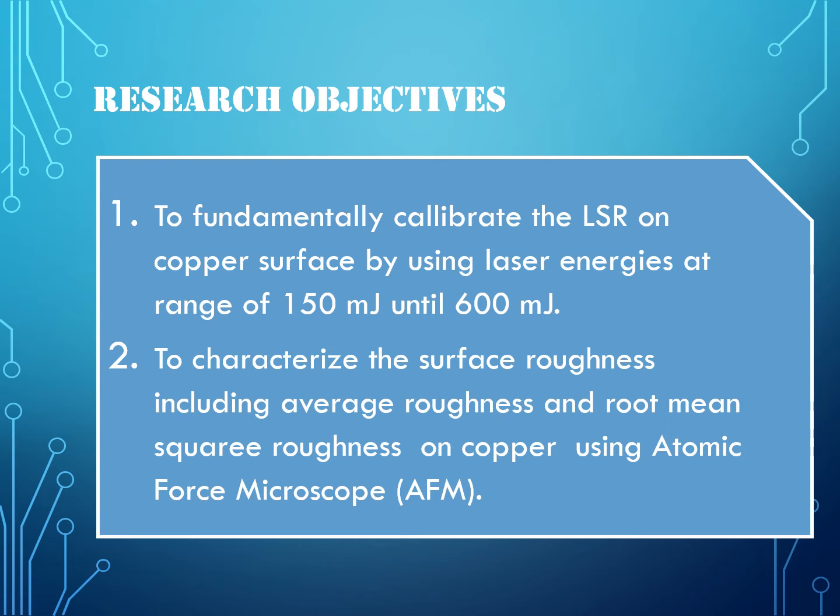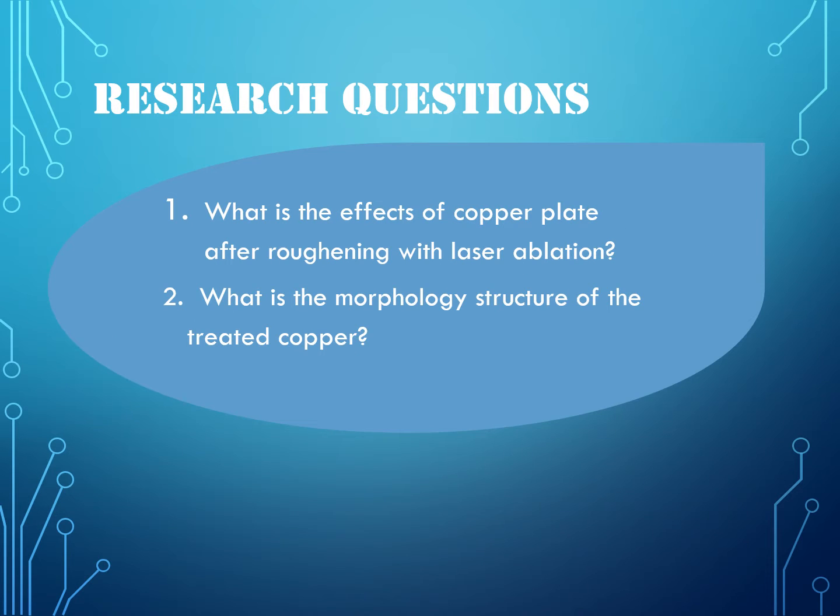There are two research objectives. First, to fundamentally calibrate the LSR on copper surface by using laser energy in the range of 150 millijoule to 600 millijoule. Second, to characterize the surface roughness, including average roughness and root mean square roughness, on copper using an atomic force microscope or AFM. There are also two research questions. First, what is the effect on the copper plate after roughening with laser ablation? Second, what is the morphology structure of the treated copper?